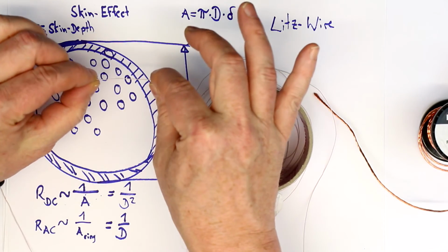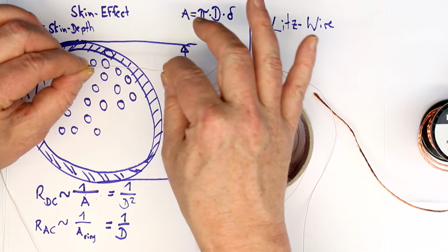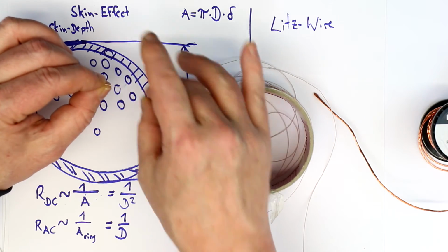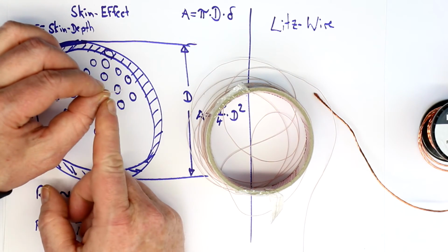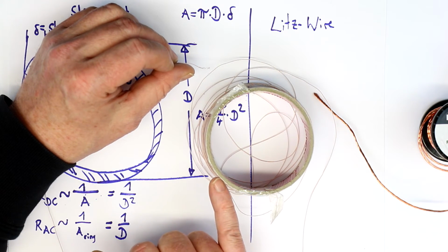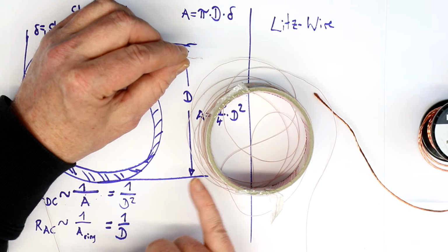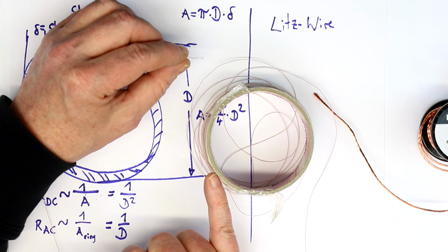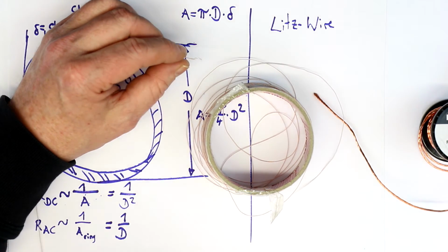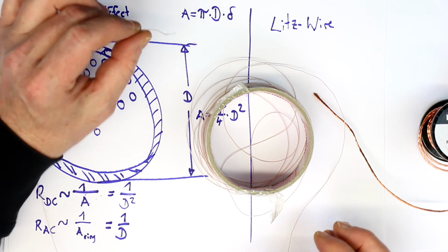This one you can already see has an outer silk layer here to protect it, because this one has very thin wires, all in all 16 wires, each 0.07 millimeters. And we even have in our shop a litz-wire with, I think, 200 single strands times 0.02 millimeters. So you can go to quite high extremes with litz-wire.